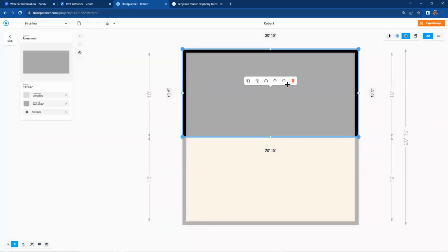Now, if I left click on the surface I just created, it has 4 corners that I can drag out and reshape it. It's sitting on the ground. It's 0 thickness, basically. So go to its settings on the left-hand side. I'm going to make this raise above my head because I'm going to make it my ceiling. So if I say raise from floor, I'm going to take advantage of the 10 feet in the back first. So I'll say raise from floor 10 feet. And then I want to tilt it. So if I select this one corner out here and say, I want this corner to be 14 feet, enter, and select this corner out here and make it also 14 feet.